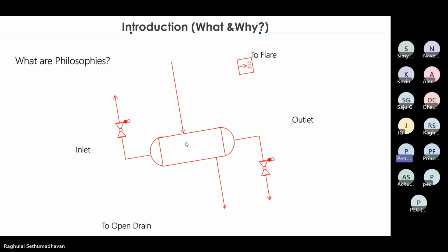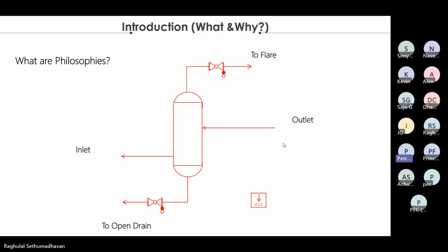Okay, something is not right about this image. See, there is a problem. I have drawn this in some software, not AutoCAD, some random app. Not supposed to be like this, right? Let's see. You okay now? Yes. Seems to be fine, or is it? No. Here, inlet and outlet directions. Vertical blind in the line to flare. Actually, it should be near to the vessel, right?